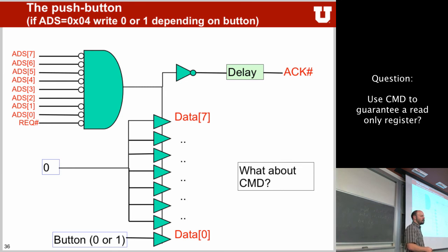Do you have another set of tri-state buffers that switch between reading and writing then? You could. Another port in the AND gate. Yeah, you can have just another AND gate here, or you can AND it in here with this one, so that the tri-state buffers only get activated if it's an actual read from the register. Else bad things would happen.